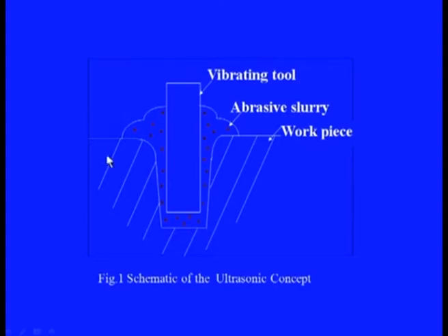Now, in this particular configuration, the ultrasonic vibration is given to the tool itself and the workpiece will remain stationary. Here both the actions will take place. The normal EDM, because of the dielectric being flown here, which is in the form of a slurry in which some abrasive particles are also suspended. These abrasive particles in turn will take part in the ultrasonic mechanism, which we have already discussed in several sessions.